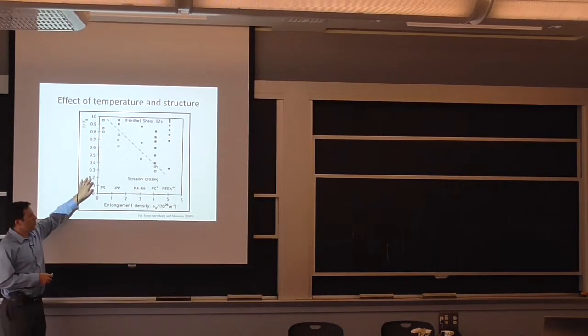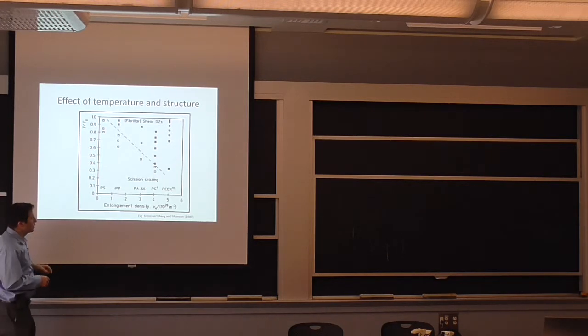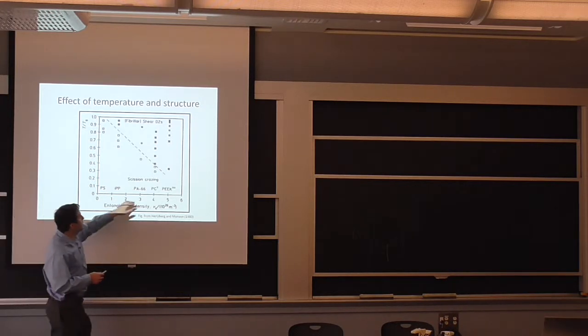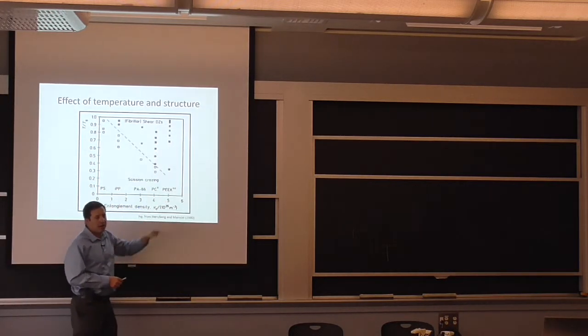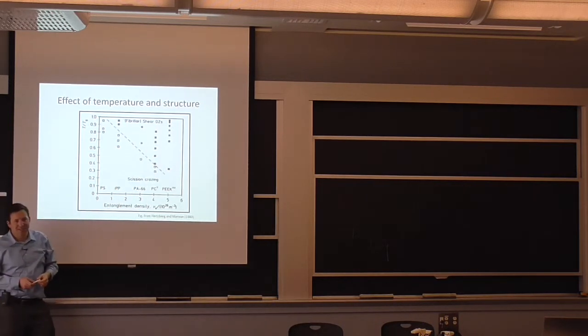And you also know the temperature with respect to the glass transition temperature, and we'll go to that next. If you have those two characteristics of the polymer, you can determine whether it's going to mostly form shear deformation or if you're going to start to have crazes.